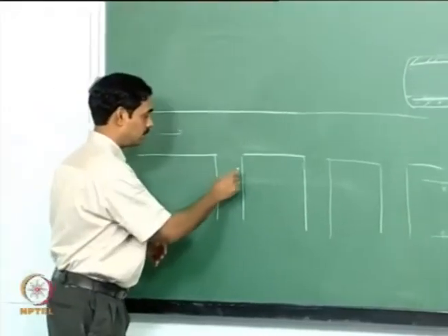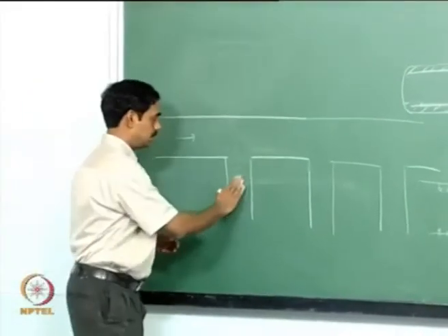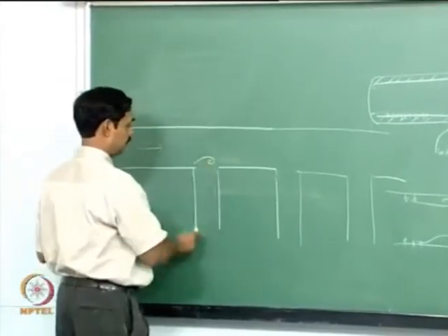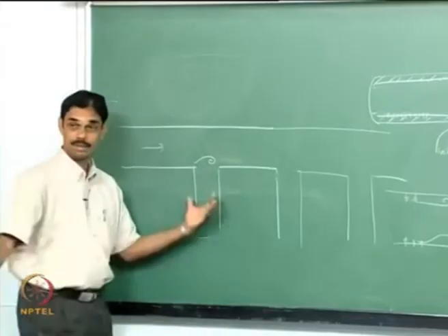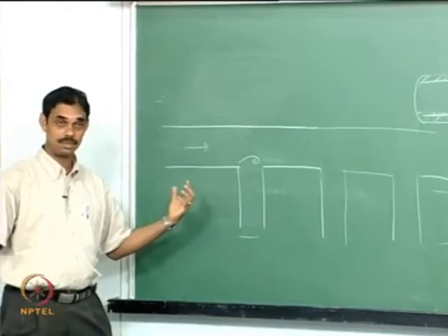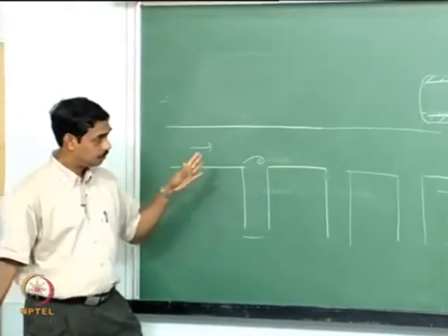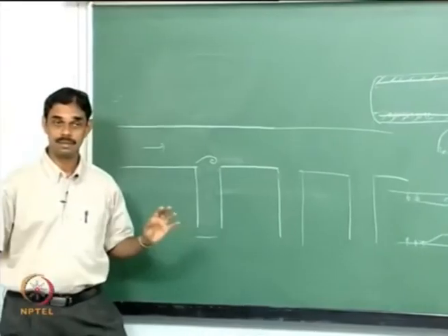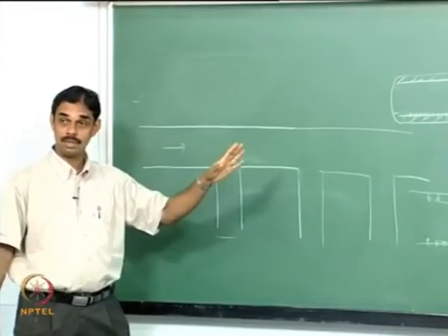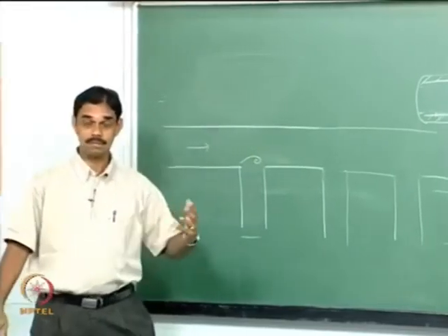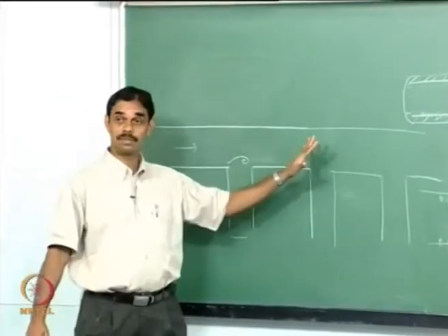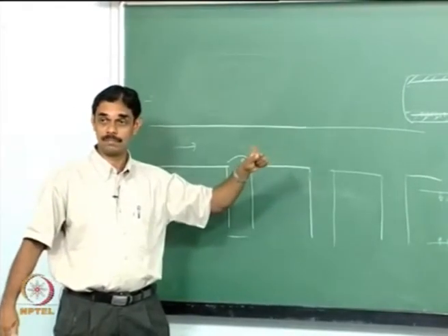So sometimes the moment you close some branches, many times instability develops, because you have vortex shedding, and now you have a resonator here, and then you have very large amplitude sound, and it will be quite strong. The ducts are very long, and the vortices are strong, they can travel long, and the sound wave will travel quite long, and as any sound wave travels, as will be discussed, it will steepen into a shock, so you can have large amplitude shock waves coming and rupturing these pipelines and so on.